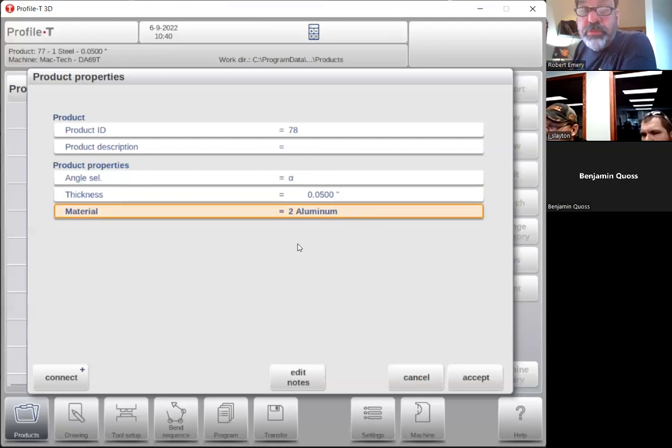Now, what's the difference with the material choices to the machine? Well, how many tons it's going to need, that's based off of the material property called tensile strength. And then how much spring back it's going to have, that's what they call E modulus or elasticity. So when we get into the material library, you'll see those two columns.